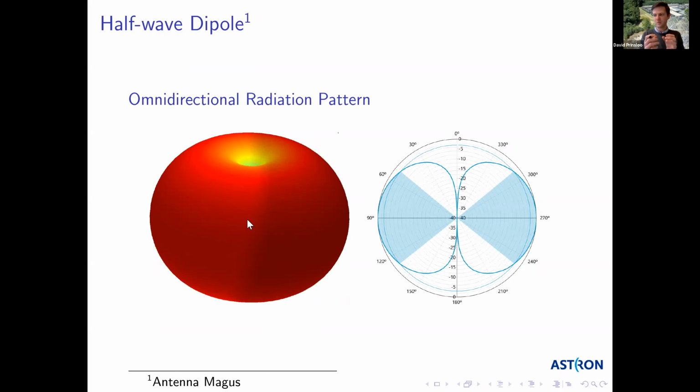So we're ignoring radial distance here and have assumed that we're showing the data on a sphere of unit radius. This is actually the gain, we can call it like that. Because also remember that this quantity is normalized to the total radiated power of that antenna. So it is normalized to its own amount of power. So we do not look at it as a radial dependence anymore. I hope that makes sense to you.